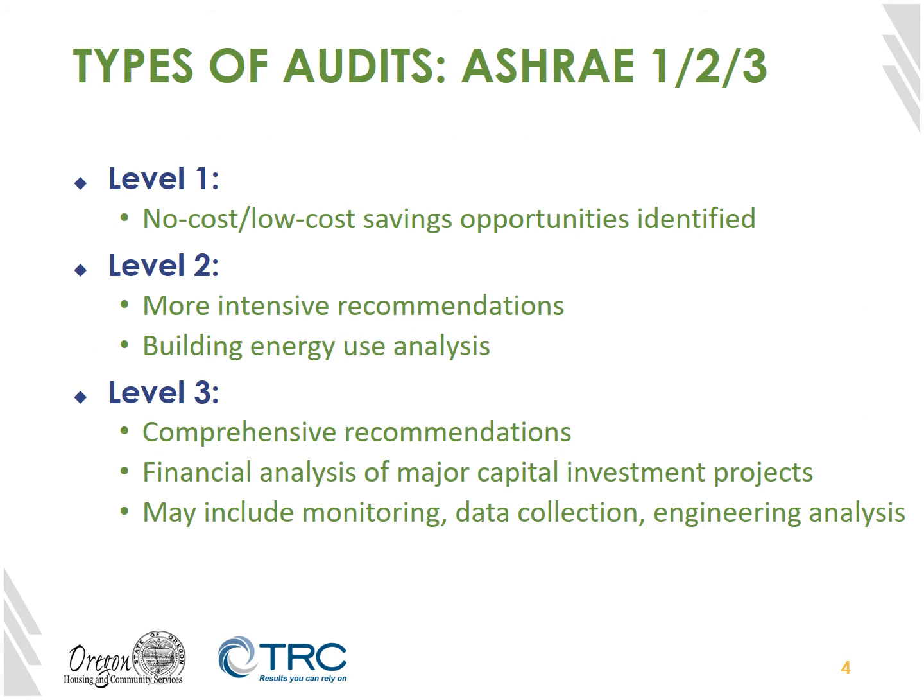Energy audits may be split into several categories based on the breadth or the depth of the audit. ASHRAE, the American Society for Heating, Refrigeration, and Air Conditioning Engineers, separates audits into three levels based on depth. Level 1 audits involve the least cost-intensive recommendations to building owners. These recommendations typically involve improving the use of existing systems through set points or installation adjustments. Level 2 audits are the minimum level required for the whole building pathway of this program.